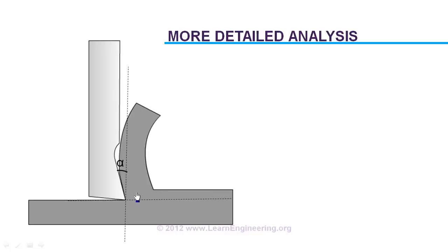During cutting operation, this chip flows upwards with the velocity Vc. And during this motion, the chip rubs against the cutting tool. So there will be a frictional force it has to overcome in this direction, exactly opposite to the direction of motion. If frictional force is present, then there will be a normal force also, orthogonal to the frictional force.